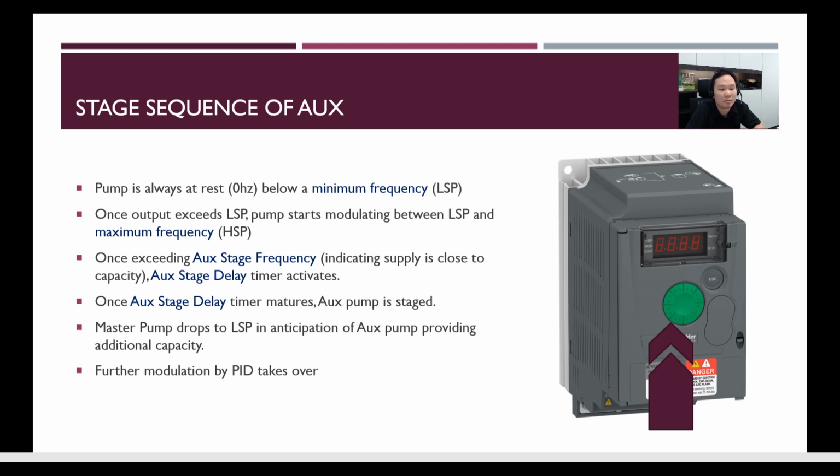And the master pump drops to LSP, which is the minimum frequency, in anticipation of the auxiliary pump providing additional capacity. So this is a very smart drive. When it calls in the aux pump, it knows that the auxiliary pump will start to contribute to the supply, so it will drop the speed to anticipate for it. Okay, and then after that, further modulation by PID takes over. So you'll see it in just a moment.